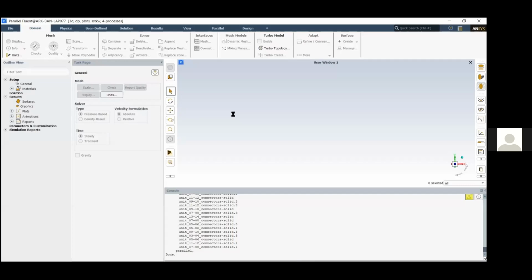How much percentage of experimental results match with this modeling technique? It depends on various factors. I cannot say it just depends on the mesh you create, but it depends on the mesh and the grid independence test, and on the actual conditions. However much you try to simulate the actual condition, we somehow make some approximations, so definitely that affects the results.